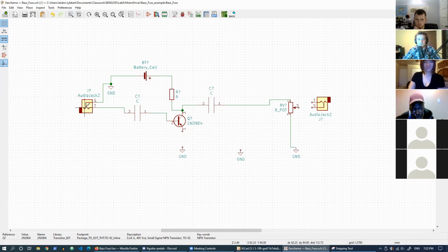The sleeve on my guitar is grounded on the guitar, and then it's also grounded here. So it'd be the same ground. Well, if you ground it at that point, it'll leave the battery on continuously. Right, and the battery provides the bias for the transistor, so it is on all the time. It's just a very low current, and no current's going through the capacitor because it's a decoupling cap. So it is using power continuously. You could put a power switch and disconnect that.